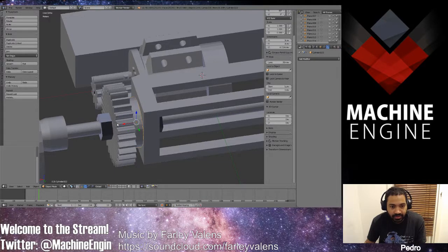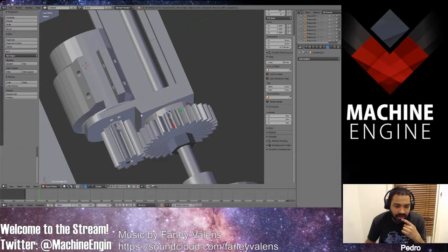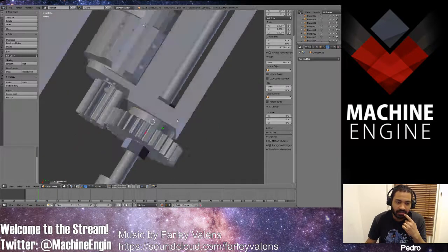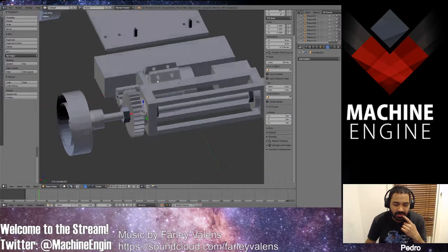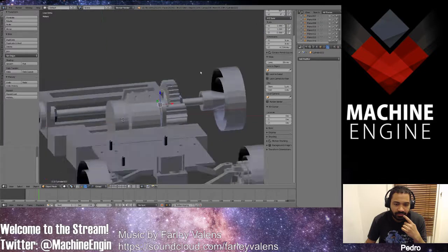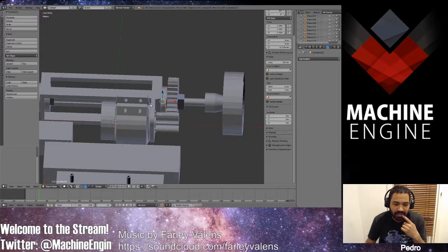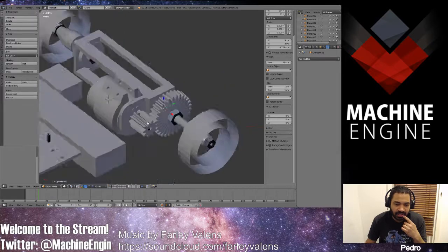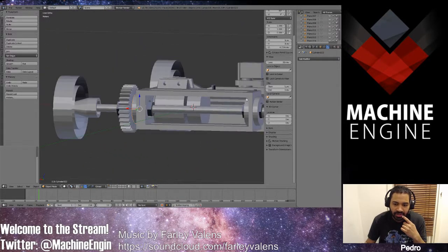Yep. So when you 3D print it, only this part is going to be overhanging, but that's fine, no big deal. Everything else is going to be flush and nice. Also this is going to be overhanging. Only here, this area is going to have some slight overhang, but it's really slight. Just these and these. Everything else is just going to print fine. Oh, and also here on the inner part, this is going to have a lot of overhang.